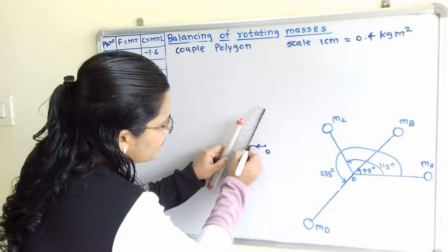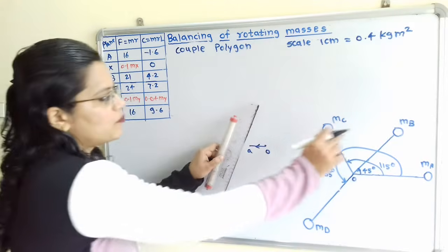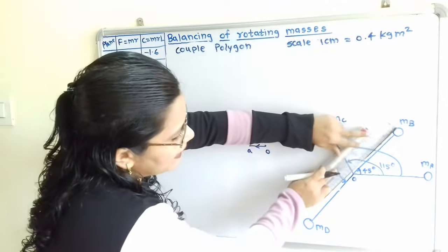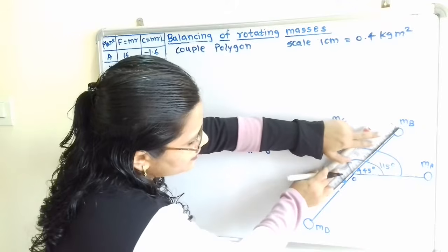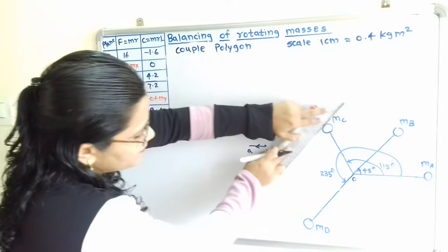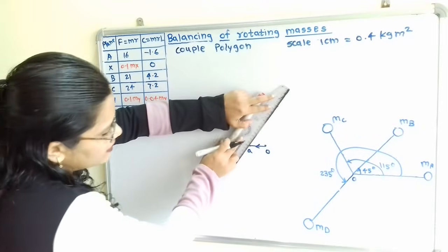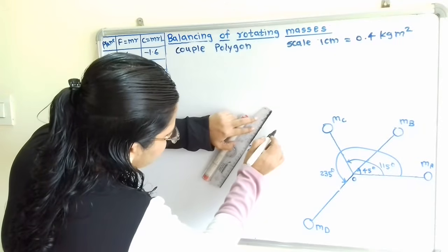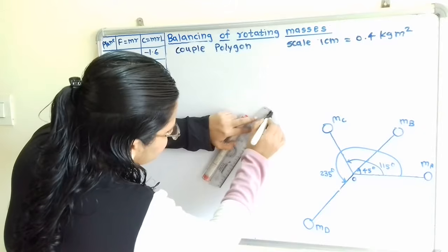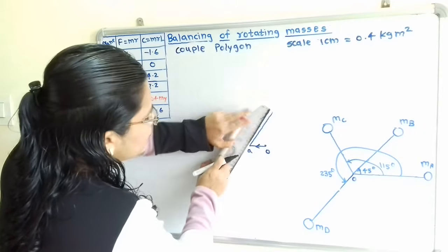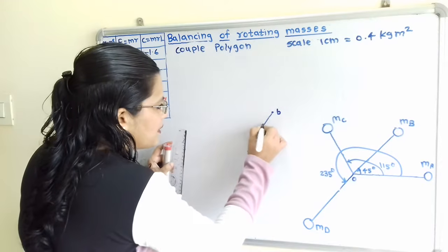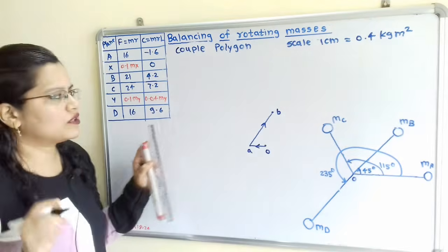The initial point will be point a and the final point will be point b for plane B. So with reference to this angular position diagram, we will transfer this line at a 45 degree. So we will take here 10.5, and now this angle is 45 degrees, so this point is point b, and now we will show the arrow also.